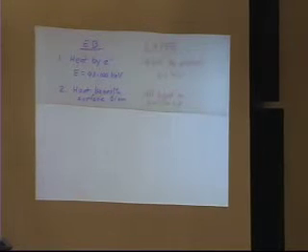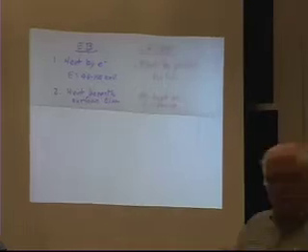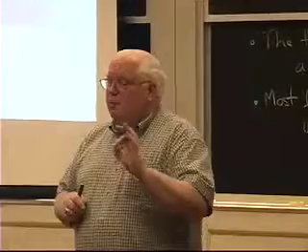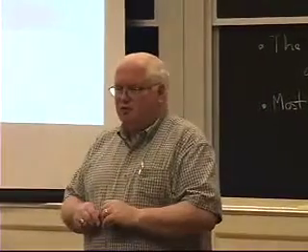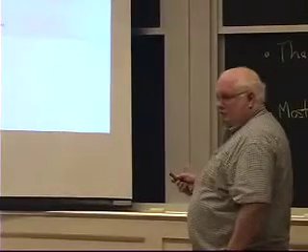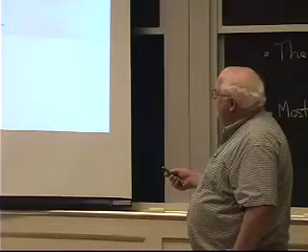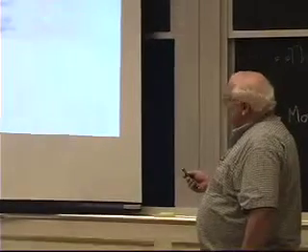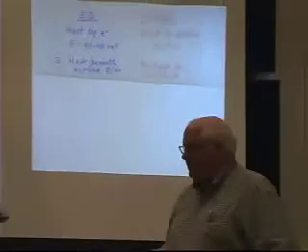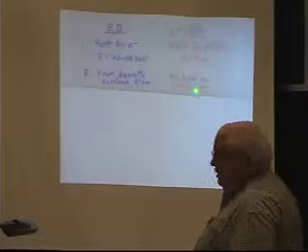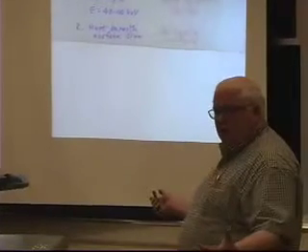Whereas in a laser, photons interact with the free electrons in the metal, and it's purely surface heating within the Debye screening length. The Debye screening length, if you remember, is like 10 to the minus 5 millimeters. So again, we've got about 6 orders of magnitude difference in penetrating capability. Now, it may not be very deep penetrating here, but it can be very significant, and I'll show you that. But in laser, it's all heating on the surface. Now, the problem with all the heating on the surface is I'm at the limit where the material can't carry the heat away anymore.